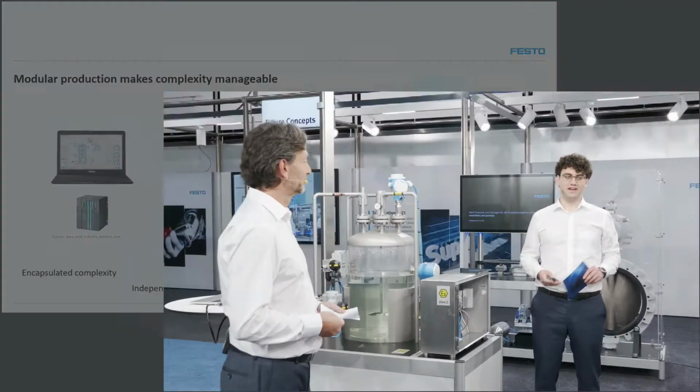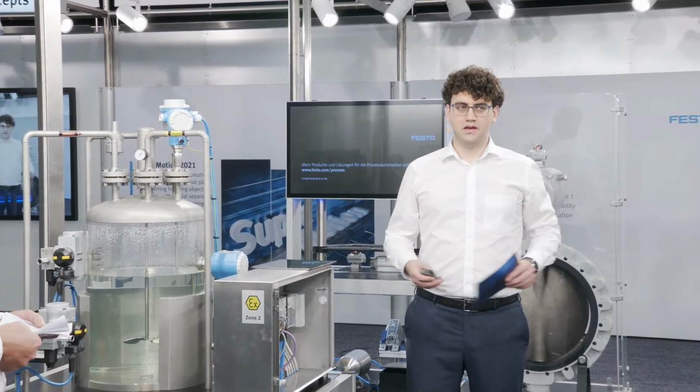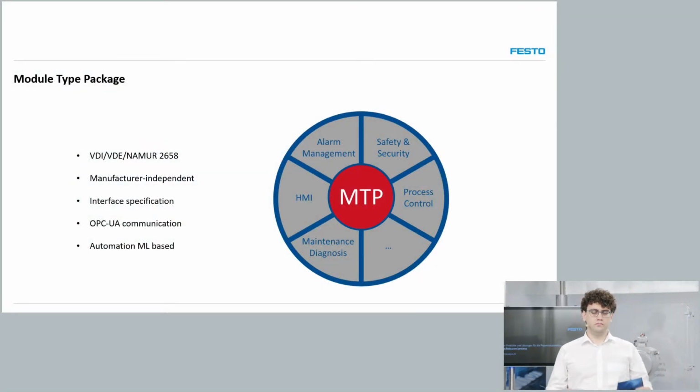Yes, there is something going on, and it's called module type package. So taking your example of a small business, we all know that in big businesses we have many people, specialists, experts working, and in companies we have special languages. So we have a company-owned language which everybody understands and which is established during the time of the work. In technical systems, we don't have this time. We have to predefine this language in order to make every control in the field able to interoperate with this above-lying control system.